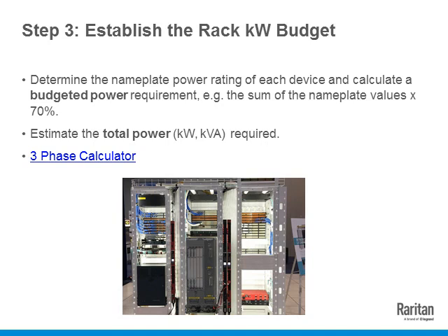But what if there's a spike? What if there's a high demand? What if there's a peak load that comes up? How do we handle that if we estimated only 50% at the rack level? So we choose a middle ground, and we come up with a number between 70 to 80% of nameplate value to be the estimated power draw.